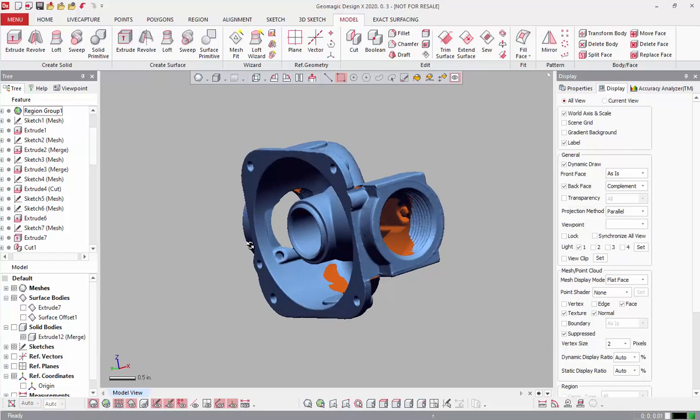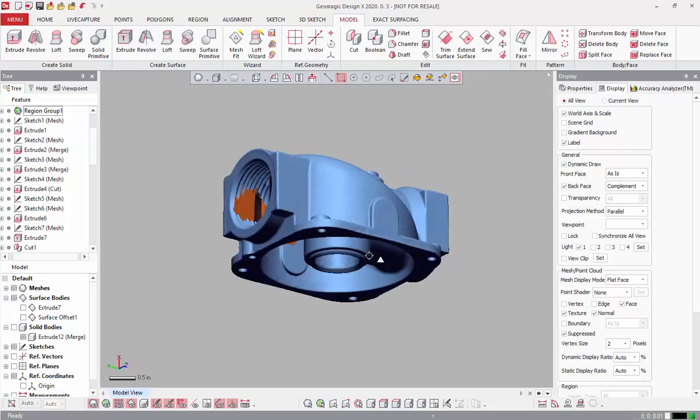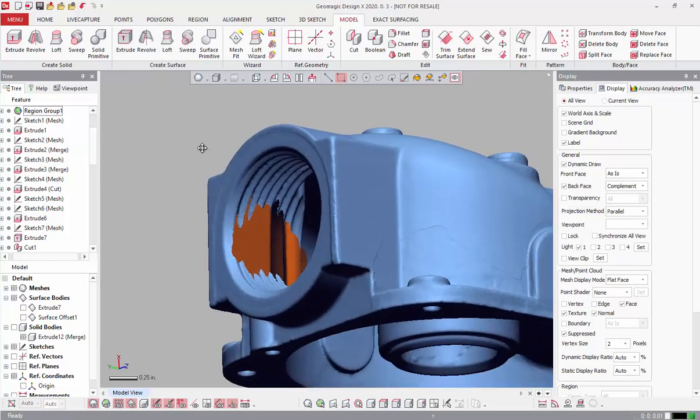Now, threads in most CAD software, as most of you are probably familiar with, are usually just visual threads, right? They're graphical threads. They're not actual geometric threads. And there's a couple of reasons for that. One is it's just much easier to render. And two, most CAD packages, SolidWorks, NX, Creo, CATIA, etc., have libraries of standard ANSI threads and whatever other metric threads. In Design X, we don't have that. Any of those libraries would just add additional gigabytes to the already quite large installer for Design X.